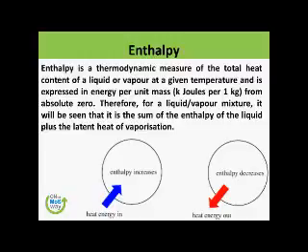So for a liquid vapor mixture, it will be seen that this is the sum of the enthalpy of the liquid plus the latent heat of vaporization. Are we happy? Are we clear on that? That this is what we are trying to do.